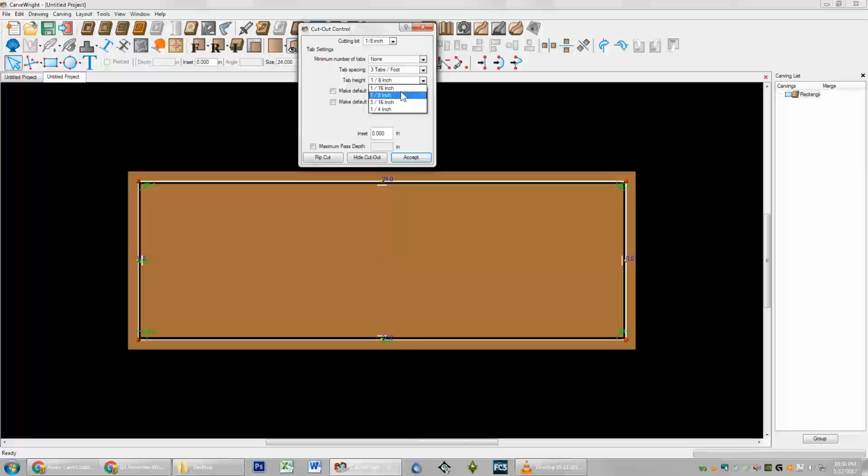And then when I'm sanding it, it's super easy to get it completely perfectly flat. So I leave it at 1/8 inch. We don't need to do an inset. I do put a maximum pass depth of 1/4 inch. That means it's going to do 3 passes on the cutout. I have missed this before and not put a pass depth.